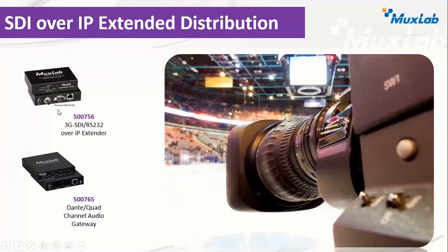You can actually go HDMI in on a transmitter of the 754 and come out of this 756 on the RX side on the SDI side, or vice versa. So it allows you to mix and match. But it is a compressed environment. It is an older product. The newer ones, of course, are uncompressed and support ST2110.